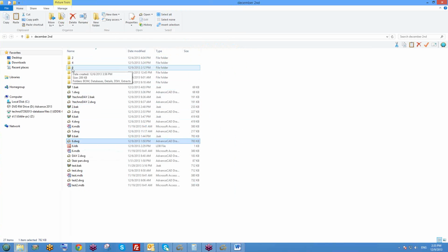So you're going to get that folder, that's 6. If you don't have this created, create that manually. You want it to have exactly the same name as your model name. You should pay attention to capital letters as well. If it's lowercase like this and you change that T to a capital letter, it's not going to work. You should respect everything.